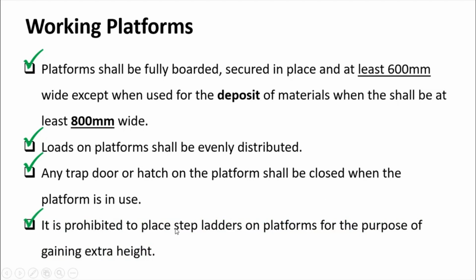It is prohibited to place step ladders on platforms for the purpose of gaining extra height. So when you have the platforms and then you realize that the work cannot be reached from those platforms, and you provide ladders to get extra height, it's not permitted, it is prohibited.